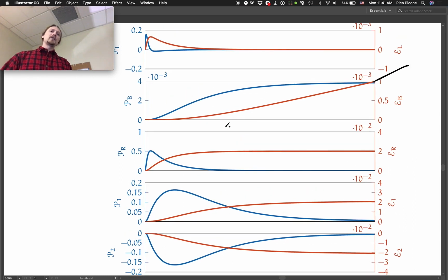So notice there's always this trade-off, and I just want to really highlight this. We're damned if we do and damned if we don't, right? At low speed and high torque, the resistor is going to be dissipating. At high speed and low torque, the damper is going to be dissipating. We're going to be dissipating no matter what. And actually, the resistor dissipation is usually the worst in a system.